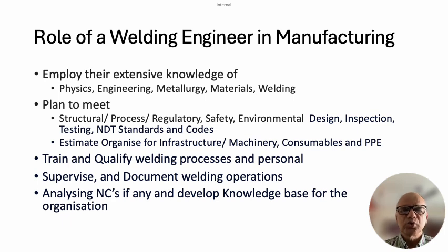If there are two nozzles which are required to be exactly 1 meter away, then you have to tie these nozzles 1 meter away and fix it onto a pressure vessel, so you require a fixture. Or you want the tray support rings to be perfectly perpendicular, then accordingly you can have a fixture or a proper selection of a process like the double operator technique, and then you choose different positions to ensure that structural integrity is also maintained.